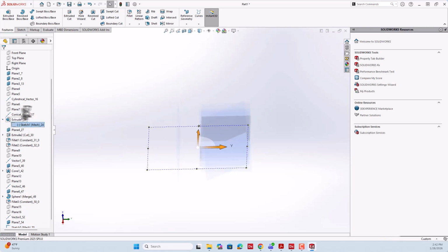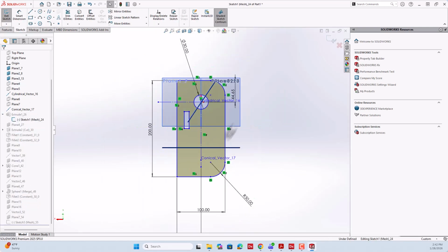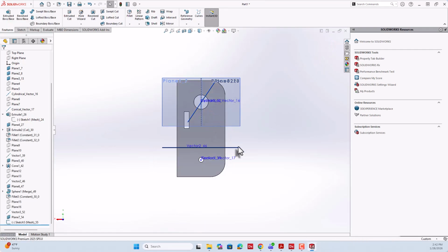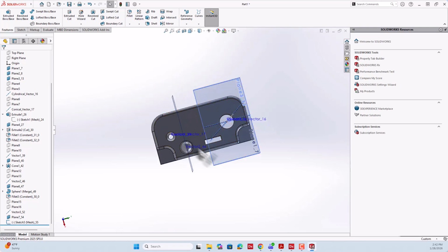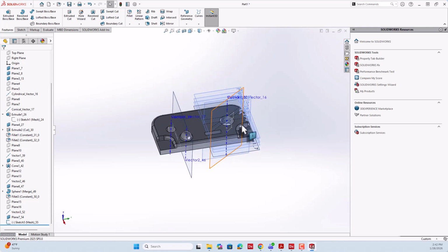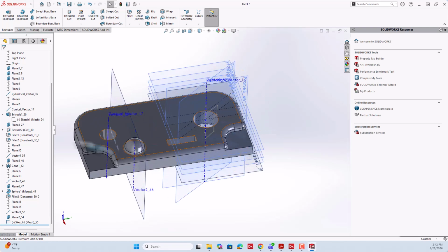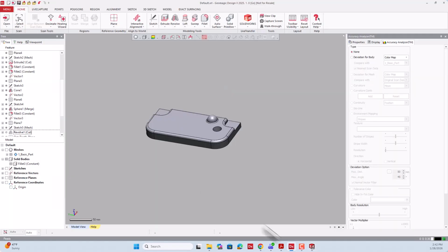So if I go in here and try to edit the sketch, we can see that all the dimensions are present, all the constraints, everything has transferred over from DesignX into SolidWorks, and we get the complete modeling history. And we have all the things transferred like fillets, etc. Everything has come over. And in case there is something like a break, you can always roll to end.